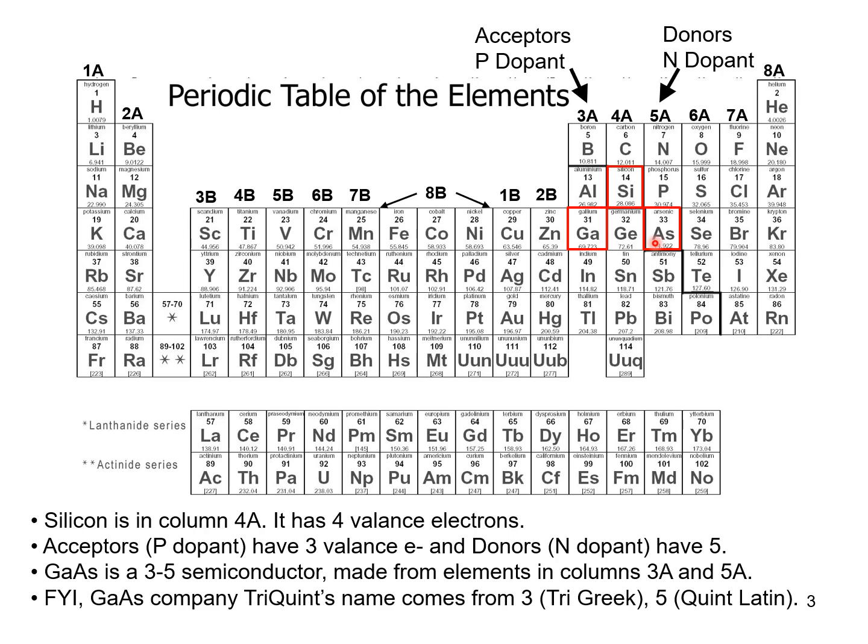One of the advantages of gallium arsenide over silicon is gallium arsenide has a much higher electron mobility, and that's very good for RF devices. So you'll often see gallium arsenide used to build high-frequency RF circuitry. The P or hole mobility is not so good in gallium arsenide, so you don't really see any P devices being used in gallium arsenide, just N-type devices that use electron mobility.